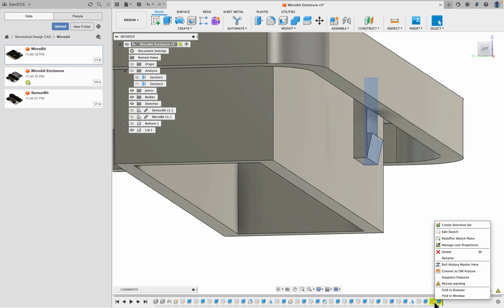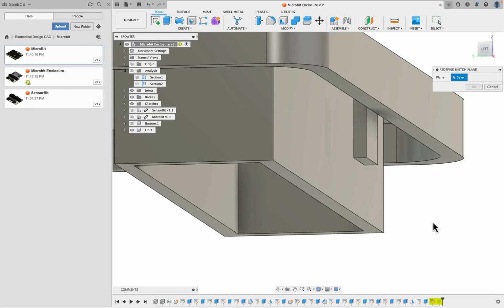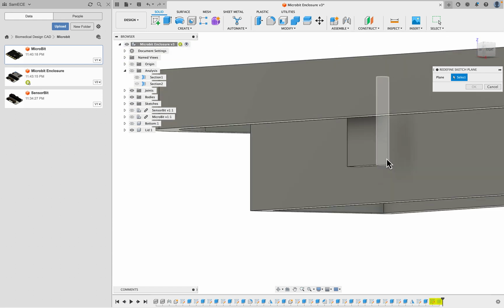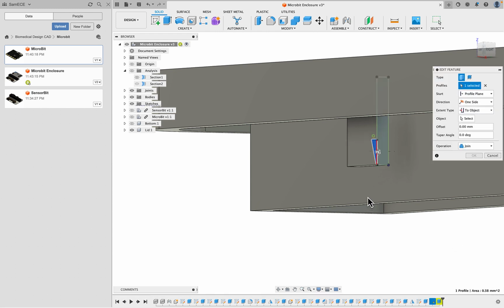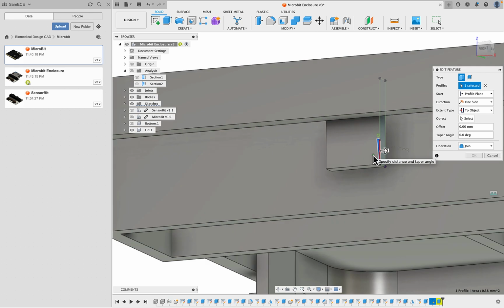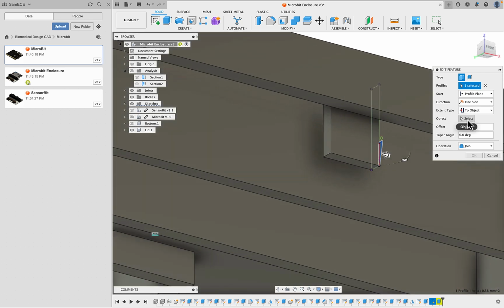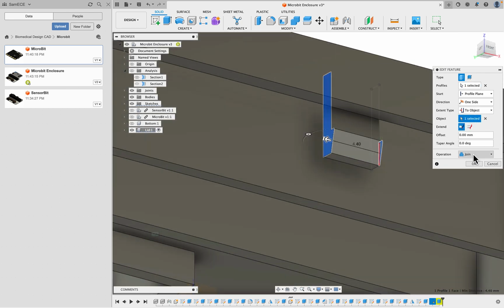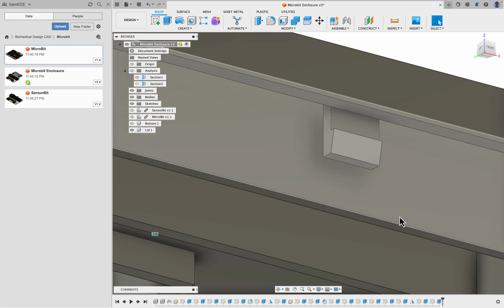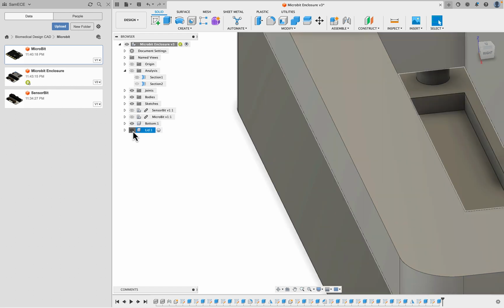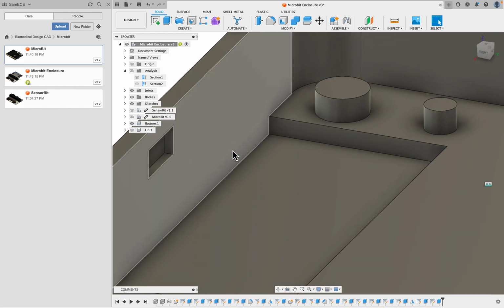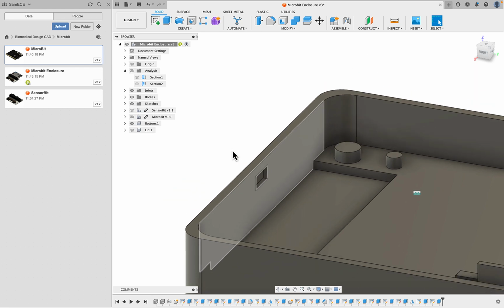Okay, then this one is a lost projection. So I'll redefine the sketch plane to be there. I should do it. Yeah. And next up we'll just edit this feature, going from there on to this side. So yeah, no warnings, everything's good, and hopefully if I hide the lid, yeah, the tab disappears. So now it's actually present in the right direction.